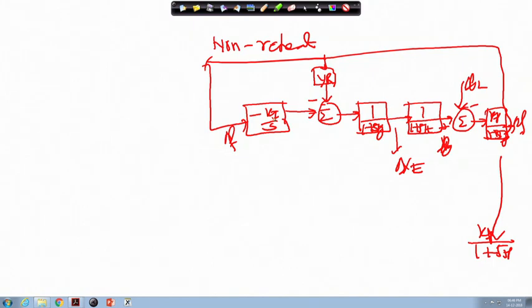There are many ways. This state variable is x1, this one is x2, this one is x3, and instead of U, because the output of the integral controller is U, we will treat this one as x4. So 4 state variables are there. From that we will find x1 dot, x2 dot, x3 dot and x4 dot, and then how to optimize K I using the concept of degree of stability.